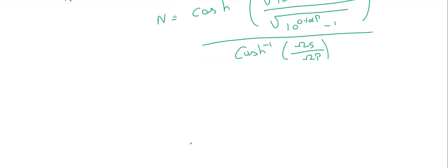Another formula, if you refer to Nagarkar, with respect to the passband gain: if it is given in dB, you can use this formula. If they give the gain in the passband edge frequency, you can use this formula.